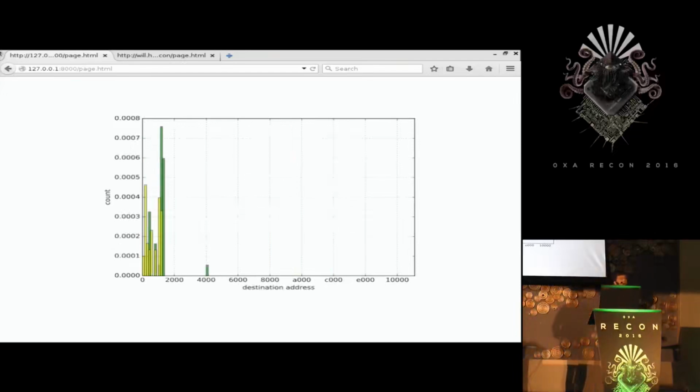And I want to emphasize, I forgot to mention earlier, these histograms are of all byte patterns that start with an 0F byte. So that's based on every single 0F sequence in the file, and it's a very small file, so you don't see a lot of noise. Normally you'd have a lot of random noise on the baseline, but this is such a small sample that you don't see it. So this is all things that match. And you see it collapses right down into a nice distribution, and that's all within the address space of the program ROM, within the size of a potential program ROM plus the loadable module.